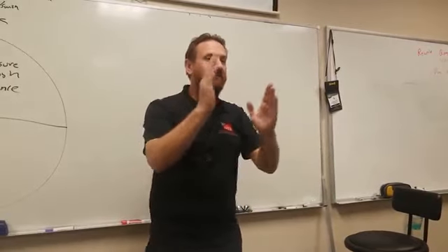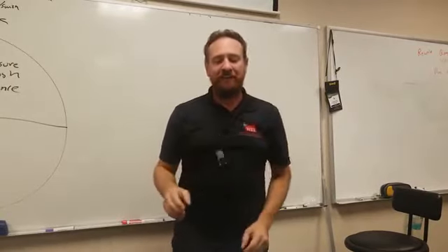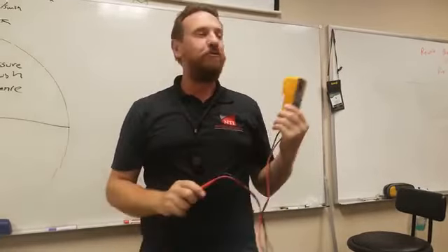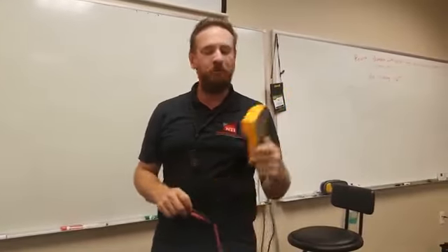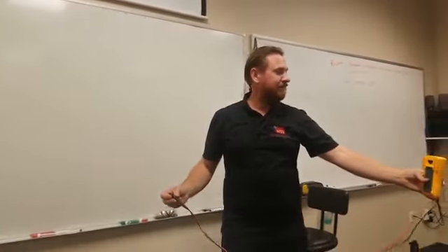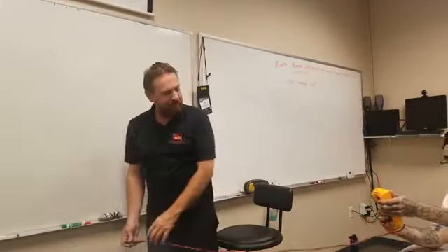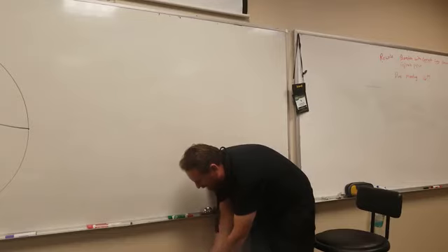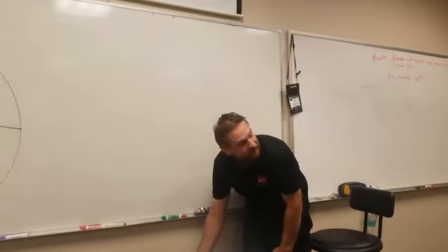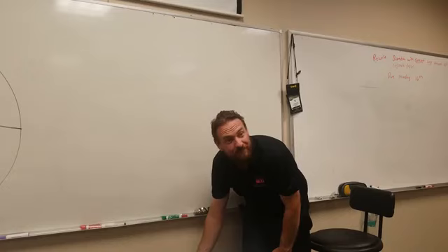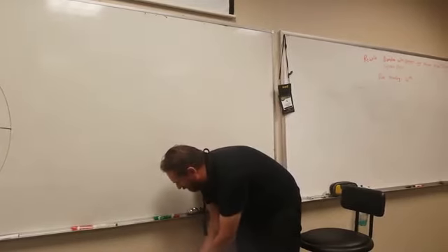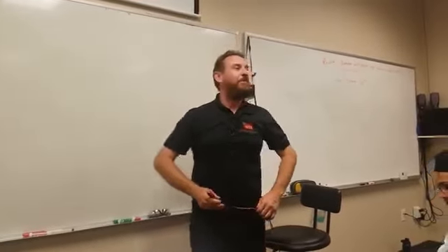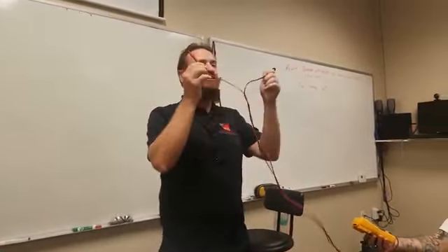Now the voltage is changing between this side and this side, but it's changing so fast, whether it's positive and negative this way or that way, the difference between those two is 120 volts. The pressure between those two points. Let's check what the pressure would be if I put both leads in the exact same side. What's the voltage? 0. Let's put both of them on the other side. 0. It's showing us 0 because there's no potential difference between where I'm using my leads.